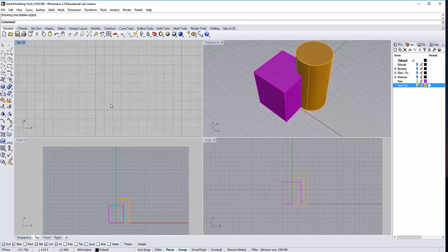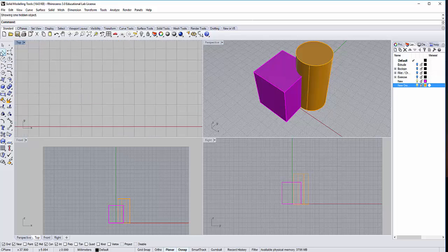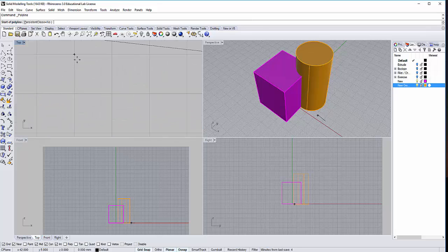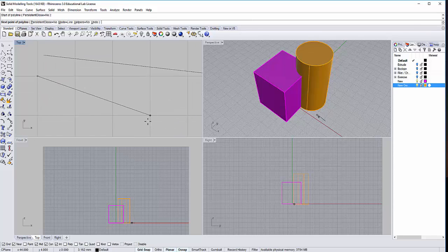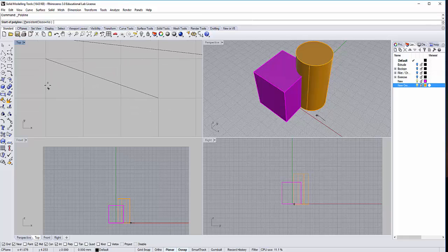I'm going to show you some other tools. Let's say, for example, you are working with a line tool, such as this. Make sure you are not in grid snap, because once you are in grid snap, can you see? It's now snapping to the points instead of where I want to, so it ends up like that. Instead of, let's say, for example, I want something here. Can you see the difference? Go try that tool, grid snap.